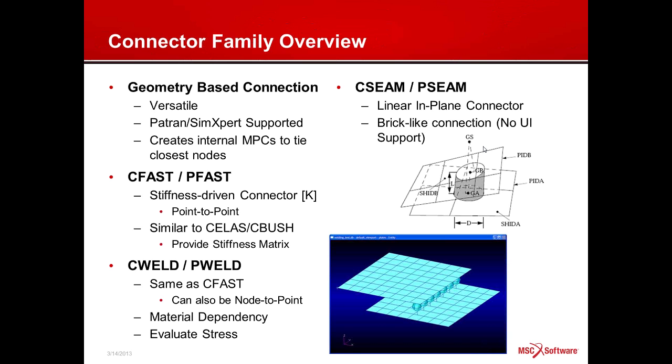Now, mind you, Patran offers the ability to do that as well, so you can create those fasteners and see where they lie in space. It's very useful. But the solver actually takes care of distributing the stiffnesses and connecting to the adjoining nodes using MPC equations internally on both sides of the plates. Therefore, the user only has to carry the location in 3D space. That's very rewarding, especially if you have to remesh either one or both of the sides and not have to worry about having matching nodes at those fastener connection locations.